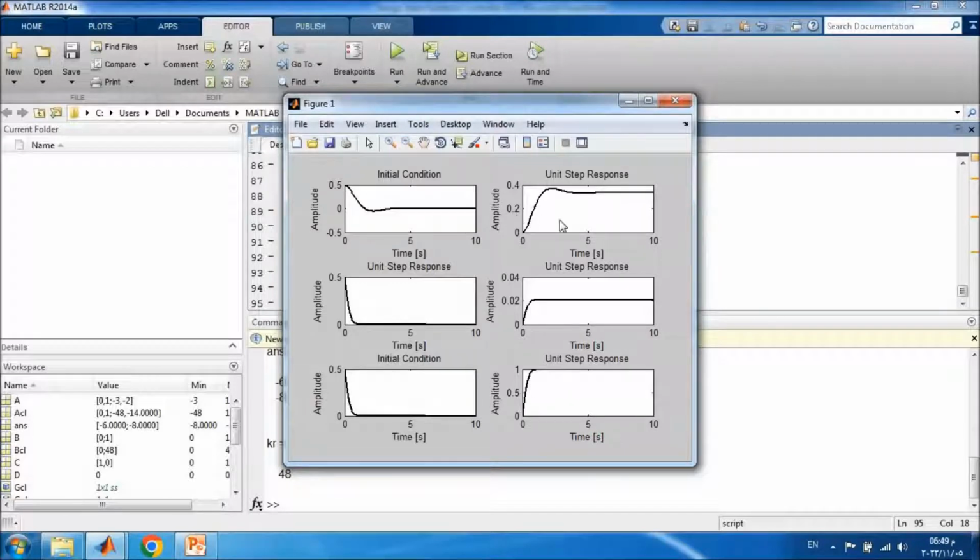Now, this is the system without controller. As we see, you have overshoot. Now, we remove the overshoot, which is good, but the system still has an offset. For the regulator it is okay, but for tracking it is not okay. Now with the DC gain, we can have the system as we want.